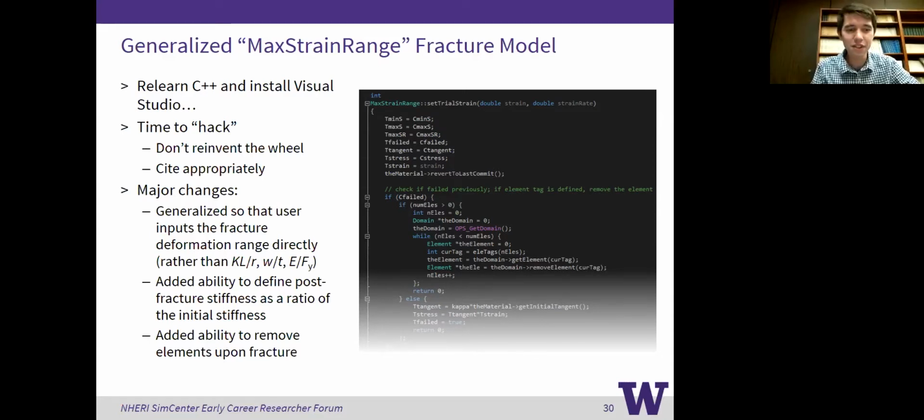What I suggest when you're reducing time steps is to take the reduced time step and do more than one. Don't just do one and then jump back up to your original time step, because more often than not, you're going to have another convergence issue and you're going to have to go down to that smaller time step again. So if you stay in that zone for a little bit longer, I think that's what the variable transient solver in OpenSees does: it spends some time down at the lower time steps and then goes back up once it's successfully converged for 10 steps or so. Okay.